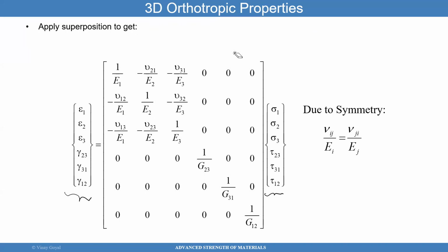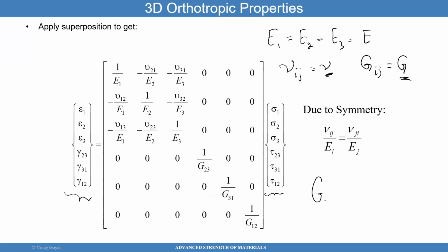And what you see here is that if it's isotropic, then E1 equals E2 equals E3 equals the Young modulus. And all the Poisson ratios become nu, and all the shear moduli become just this one. And in this case, for isotropics, you also have this relationship that relates everything else together. So that's how you calculate the strain-stress relationship.